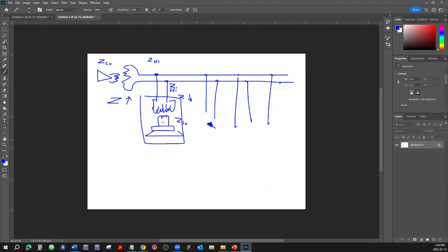So let's say this amplifier has a capability of, well, let's get a round number here, 100 watts. That's the capacity of the amplifier. All right. And the transformers on the speaker stations have taps and they are labeled.